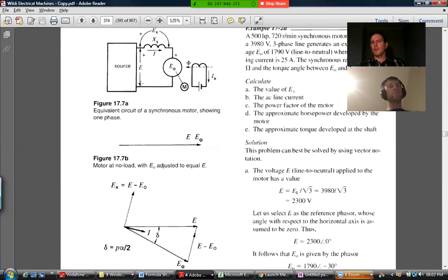Whereas when you're visualizing this thing now as a motor over here, typically you're visualizing it as if current is coming out of your grid. The voltage vector across this thing is now the other way. So the two phasor diagrams look similar, but there's a hidden difference in that the one has the current defined coming out of the grid, the other has the current defined coming into the grid, which actually changes the nature of that voltage vector across this thing when you draw the phasor diagram.